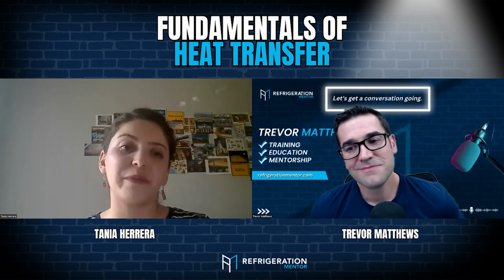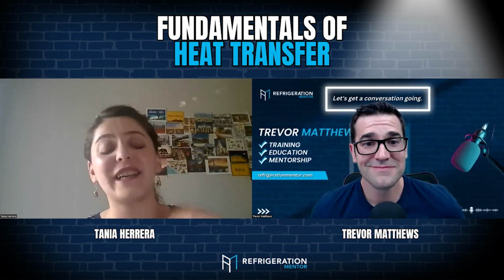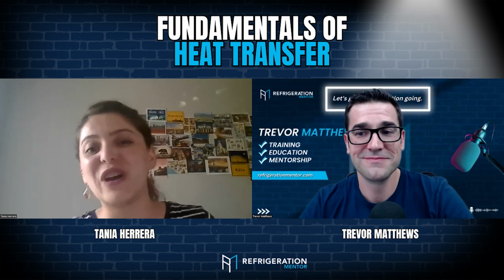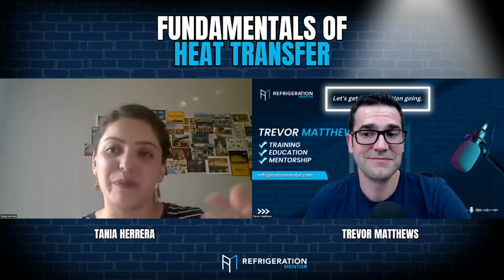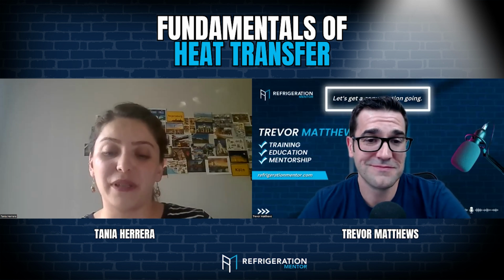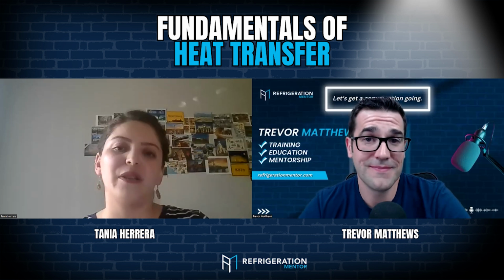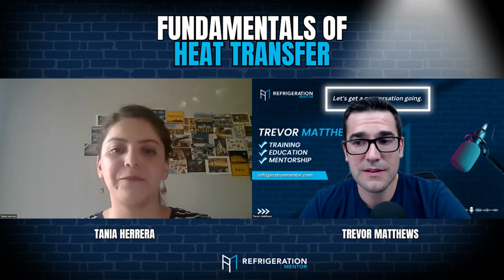I think it will be to take into account that nothing is free. I can give you more capacity, but maybe the size of the equipment will have to increase, which will be more expensive, or I will have to use a bigger motor that will have more power consumption, or I will have to decrease the ambient temperature. Sorry, the evaporation temperature in the case of evaporators. So there is always an option, but it's not free.